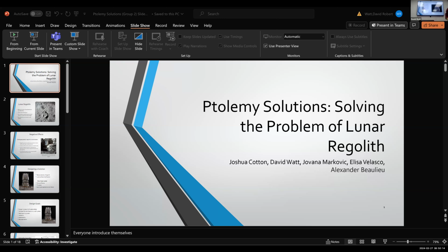Now onto that attachment. Once again, we'll attach it right to some of the shielding of the payload on the lander. The attachment of each railing system involves 2 separate pillars of the railing itself. Each pillar has 8 fasteners. These are once again blind rivets.